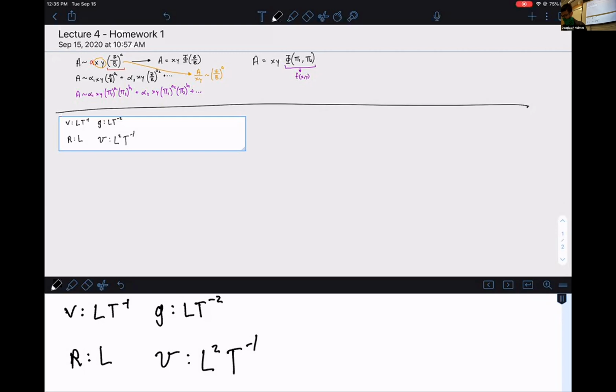And I kind of took an intuitive guess here. They define two densities here, your density of the ball and your density of the fluid. Just intuitively, heavy things sink and light things will float. So I made a guess that it's a buoyancy problem, dependent on the ratios between these densities. Rather than defining each of the densities as their own terms, I set up rho B over rho F as already a dimensionless ratio. So those were essentially the way I set up and defined my variables.